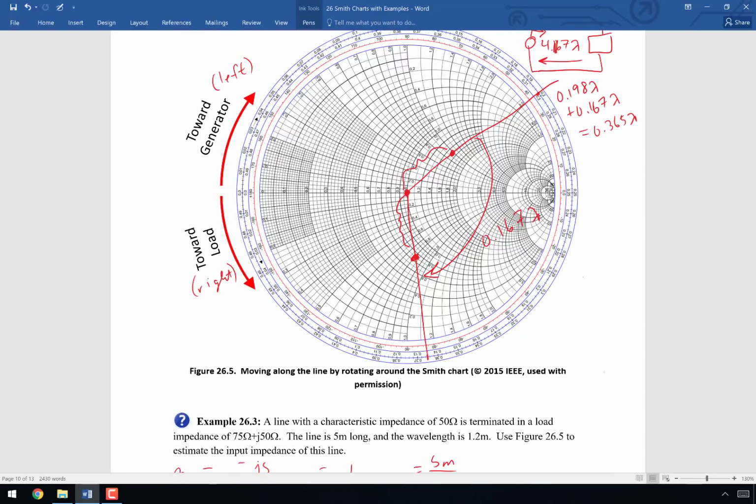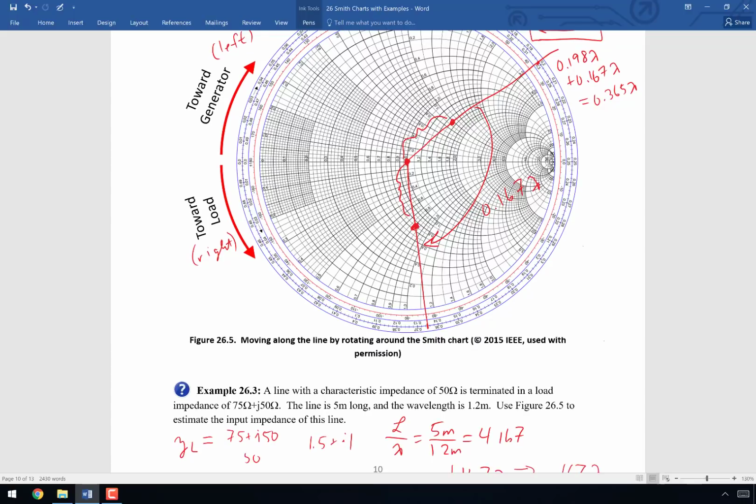And that's going to be the input impedance. I've run out of space in the bottom here, but I'm going to say Z sub n, which I pull right off the graph. Z sub n is going to be 0.75 minus j0.8. But remember that that's normalized, and now I have to unnormalize it.